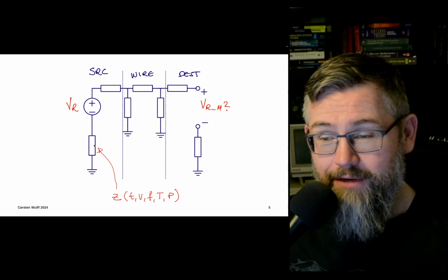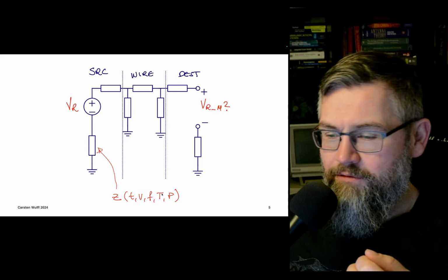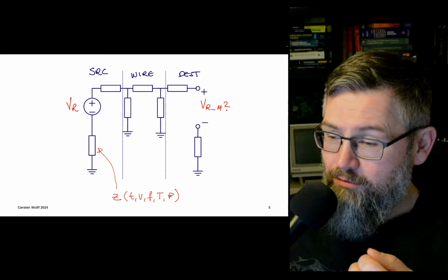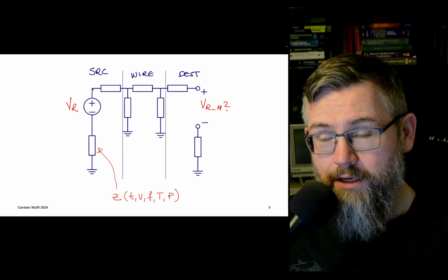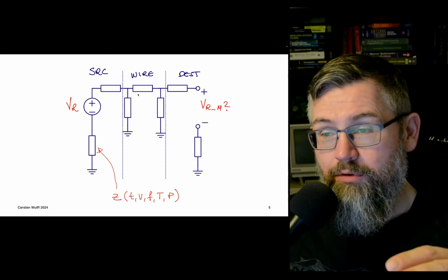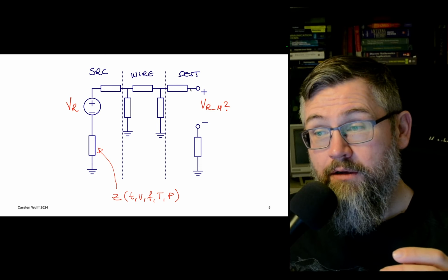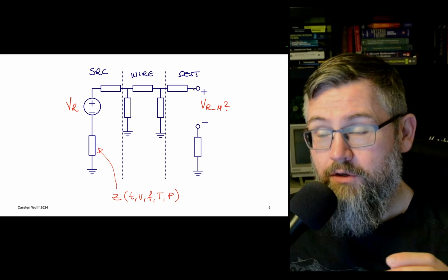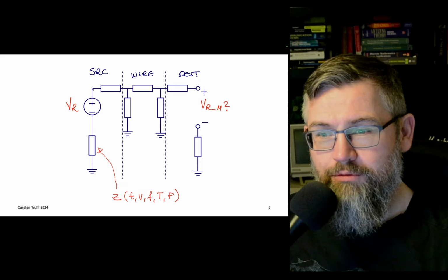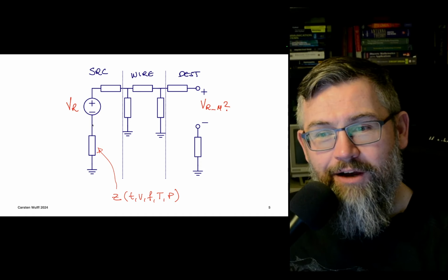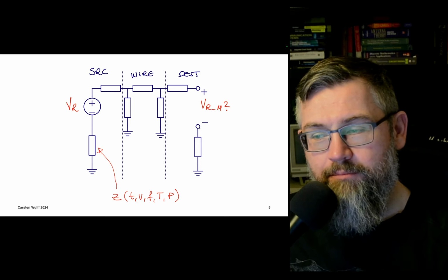You can actually have an inductor here, and you can have an induced voltage in that, or induced current really, and that impedance could be dependent on temperature. It could be dependent on process, it could depend on a lot of things. So if I now start with my node where I know I have 1.2 volt locally, and I distribute that on a wire across the chip, then the wire will have resistance. And when I get to my destination, if there's no current flowing in the wire at all, then at the destination, the plus sign here, that will be at the same potential referred to the local ground here at the source, as it is at the source. But the local ground might not be the same because it might have a different impedance.